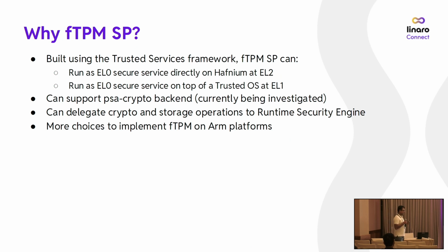ARM 8.4 introduced secure EL2, which is virtualization in the secure world. Hafnium is the secure partition manager core reference implementation based on the FFA specification, and Hafnium runs at secure EL2. If any of the ARM platforms support secure EL2, then fTPM SP, which is running at secure EL0, can work with Hafnium running at secure EL2 without the need for a trusted OS running at secure EL1.